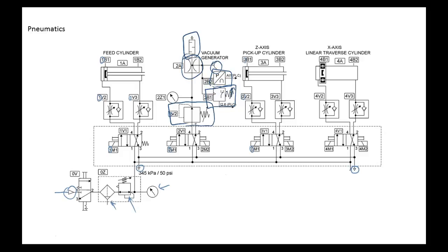What's the symbol inside? This one, that's a symbol for this. So what it is, it's got a single pole double throw switch in there. One of them would be designated normally closed and one of them would be designated normally open. So that one would have quite a bit of wire connections available to us.